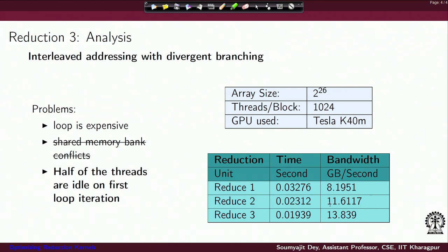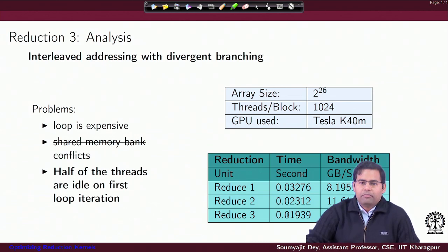So, what is the bandwidth in GB per second consumed from the memory? As we can see, with the reduction of shared memory conflicts, I have higher bandwidth and reduced execution time as an effect of that. All the acceleration is primarily due to the increased memory bandwidth exploited by the code, which is reducing the timing. I hope this is clear. To repeat, the reduced timing is due to the increase in memory bandwidth that the program is able to exploit.